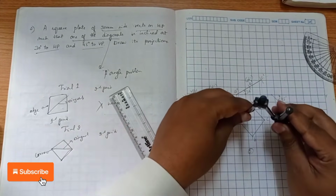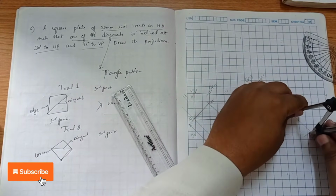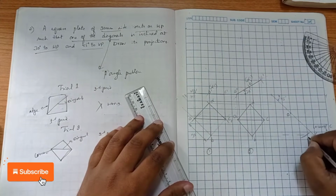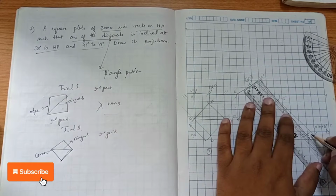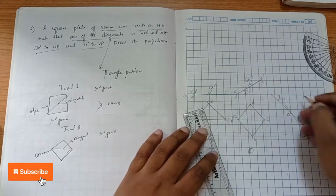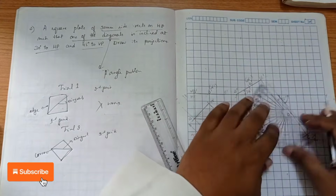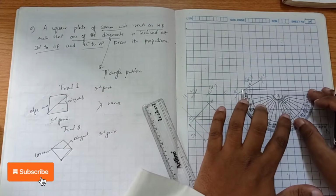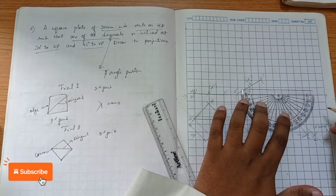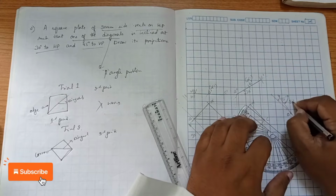Now the second arc length from A to C, measuring from A to C, cut another arc. So this point is C. So now we join this. This is where the point is joined, then extend. Okay, and then you find out this angle. So this angle is your beta angle. So here the angle I am getting is around 55, 56, 57 degrees. Okay, so 57 degrees is my beta angle.